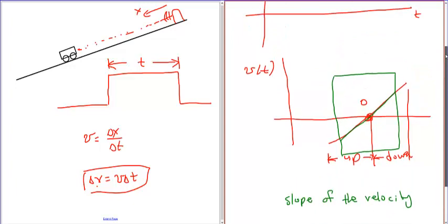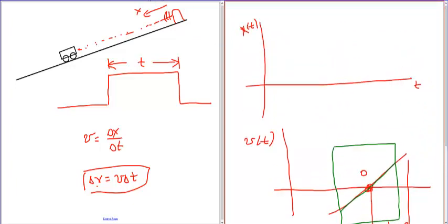Now, one thing to point out is that what we're measuring here is position. It sends out a signal, comes back, sends out a signal, comes back, and there's what we call the sampling rate. If we have a sampling rate of 10 hertz, that means we take a sample every 0.1 seconds, so 10 samples per second. That's what hertz means. Hertz actually means cycles per second, but as a sampling rate, we're going to end up using 25 hertz just to get more data points.